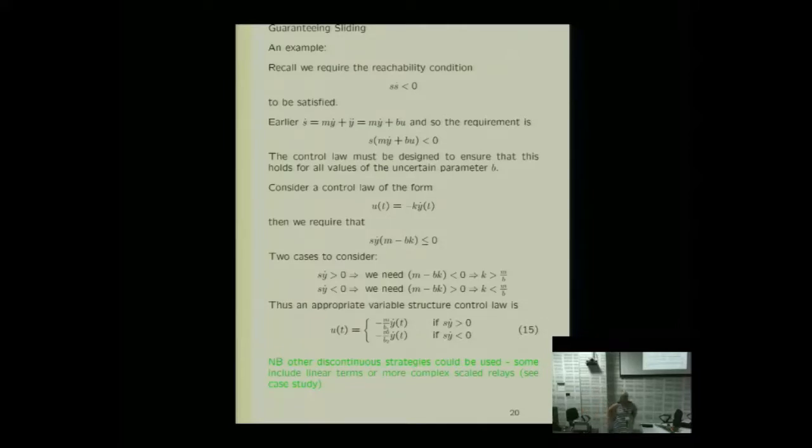And there isn't really a right or wrong. You know, if you look at the literature, you see many different approaches to solving that reachability problem. With everything I do, all the way through the controllers, right to the end of this course, you will see my approach is always to cancel anything I know that I can deal with directly with the control, because that makes my control maximally efficient. Okay, so if there's something there that I know is impacting and I can measure the signals associated with it, I get rid of it.